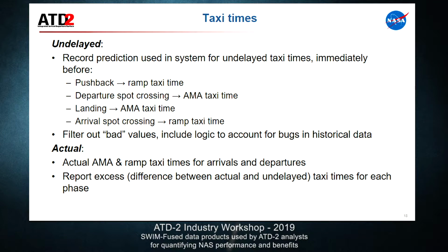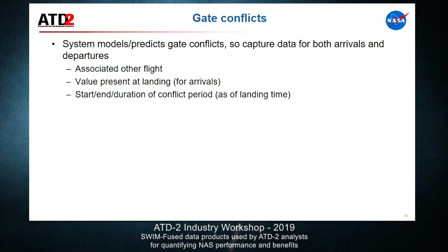Actual taxi time, as I said. So then the excess taxi time, which is a really important metric for our scheduling engine. Keep track of that for each of these phases of the operation on the surface. Gate conflicts, this is an issue that came up several times. It's obvious, it's always a huge question. It's always the zinger or the gotcha that people raise.